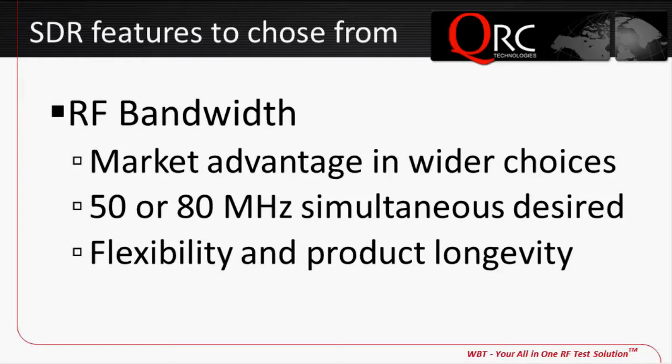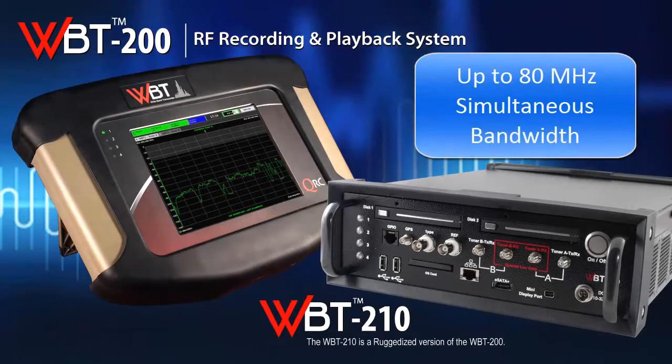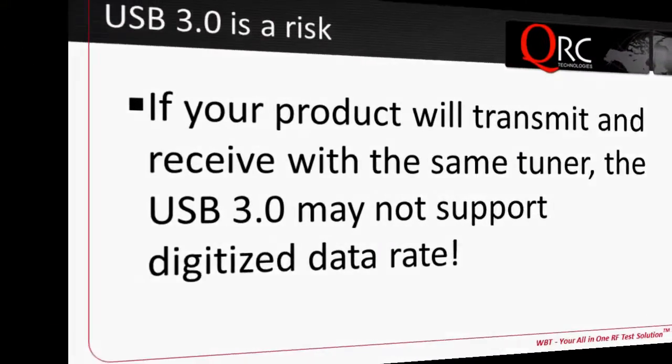Many SDRs are available with smaller bandwidths, like 16 or 32 megahertz, but the market advantage of flexibility is with the wider bandwidths, like 50 or 80 megahertz of simultaneous bandwidth. Your product will be more versatile and able to demodulate wider signals with wider bandwidth tuners. For example, the cellular technology LTE would be nearly impossible to demodulate with a narrowband SDR. A wider bandwidth accompanying a wider tunable range also increases the flexibility for the analysis of the wireless Internet of Things in our communication industry.